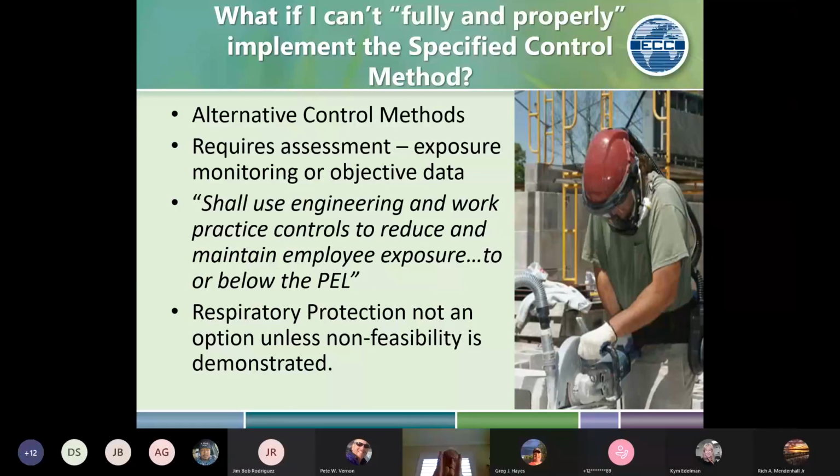So you can't sample at 2 liters per minute, for example, with an SKC aluminum cyclone. The requirement is 2.5. If you vary significantly from the specified flow rate range, then the dust size distribution that you're going to be collecting is going to change.